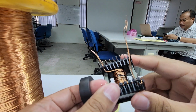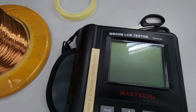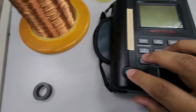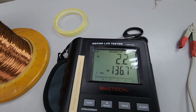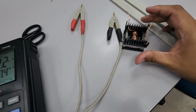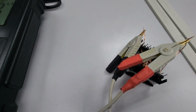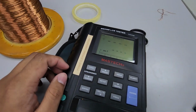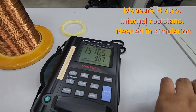So now we check the inductor. This is an LCR meter, basically an inductor, capacitor and resistor meter. So you just turn it on. Should be no problem. So let us connect these two. This port together. I have connected the terminal, so you can see here. Wait until it changes to inductance.